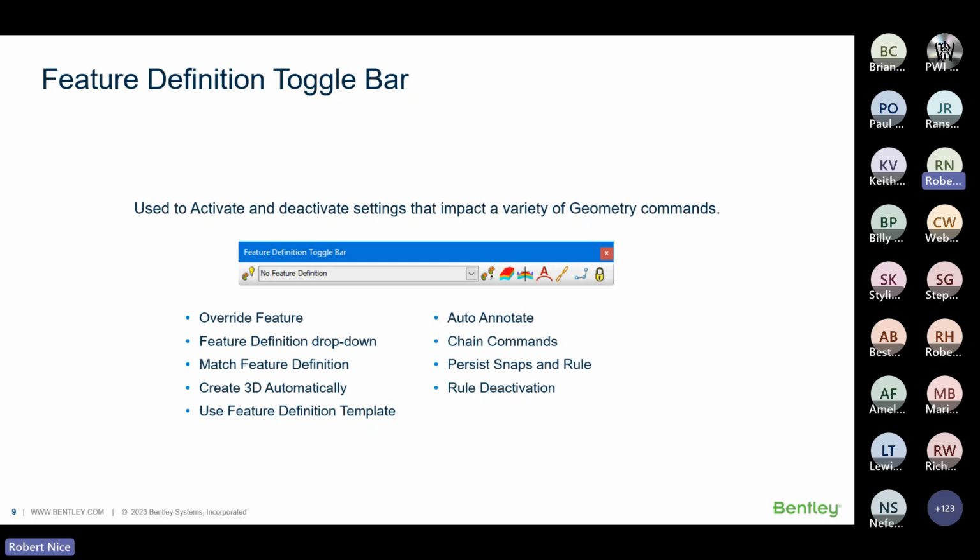And the locks, there are very few now. We do not have right lock. We do not have pen and pencil lock, for instance. Remember, we used to do that, which you probably still do. Graphic group and all the rest of them still exist in MicroStation world. But of these locks, pretty much the only one that is useful is auto annotate. If that is on when you place something, it has an annotation group attached to it.